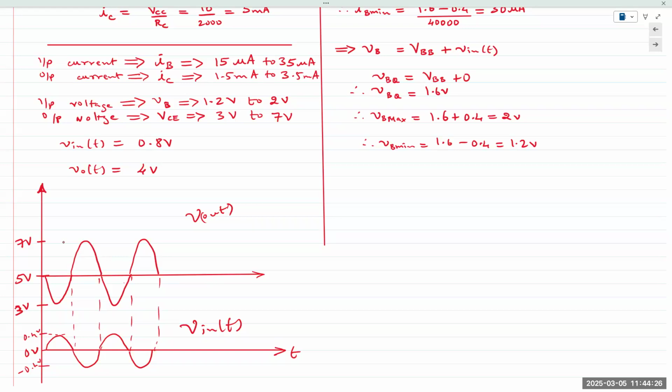If you want the pure AC signal, but you have a DC component on it, you would hear the AC sound. Let's say you're playing a song, you'll hear the song, but in the background, you'll hear a buzz. You've got to remove that 5 volt DC. And that's where the negative clamper would play a role. You would add a negative clamper at the end of the output of this amplifier with a minus 5 volts. So it will shift and remove that plus 5 volt DC. Okay.